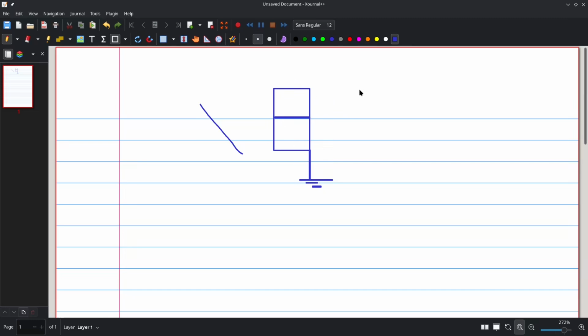But in case of common anode, it has to be in form of VCC. That means all these will be 0 for it to be applied with 5 volts, positive 5 volts, for instance. So all these will be 0, 0, 0, 0 for the perfect connection to turn it on. So it's when it is 0 that these LEDs, our A, B, C, D, they are all LEDs, are on.